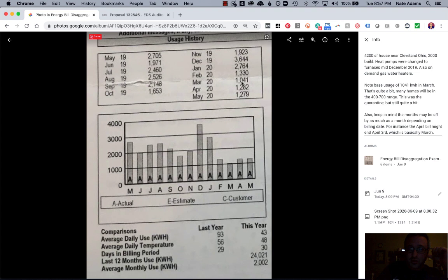Okay, so 1,000 kWh a month is their baseline now. So anything beyond 1,000, or let's call it 1,100, something like that, that is getting into cooling. Now, this house, I had an unusual piece of information because they had Carrier Infinity controls, and I'm very familiar with that stat, so I went and looked at the usage.